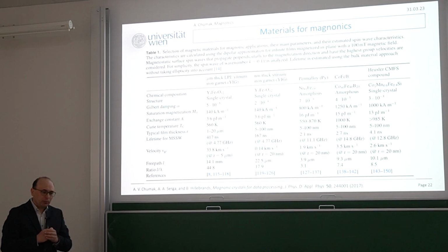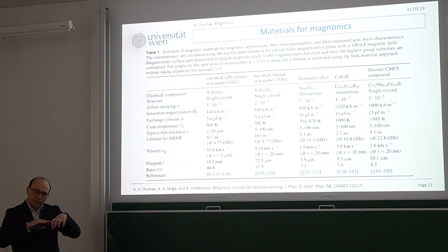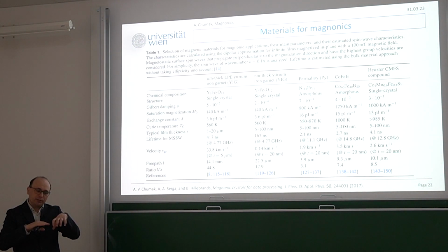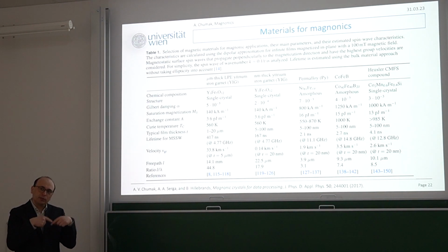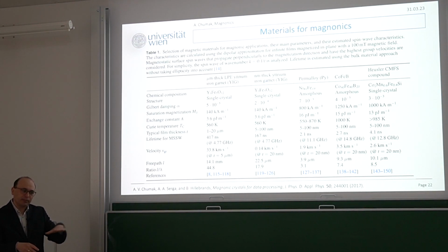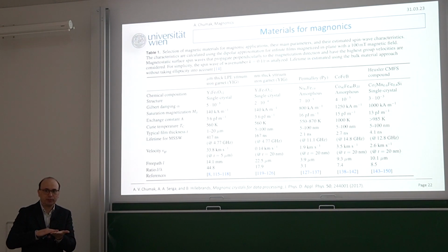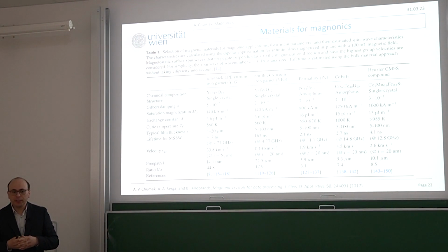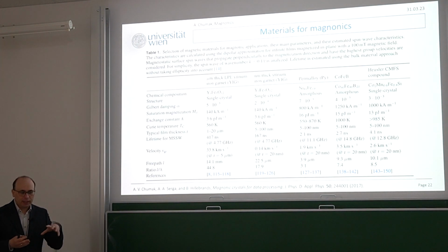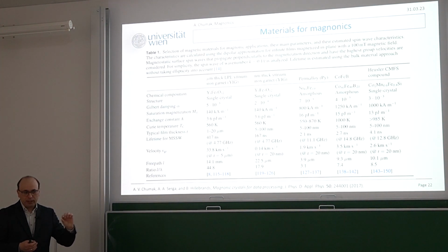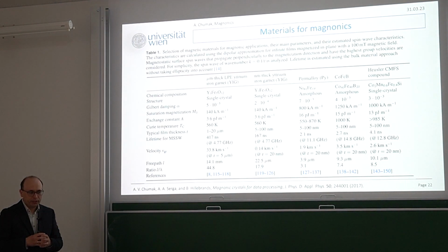And the problem is that when you start doing it, gadolinium ions from the substrate mix in. They go into the YIG, and also the interface between YIG and GGG is not very clean. So there may be different contaminations and other things. Therefore, the interlayer between YIG and GGG is an issue.